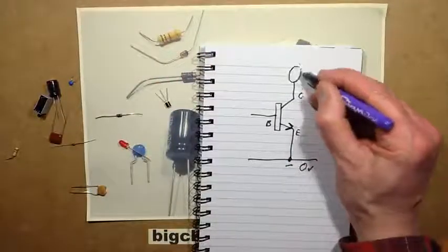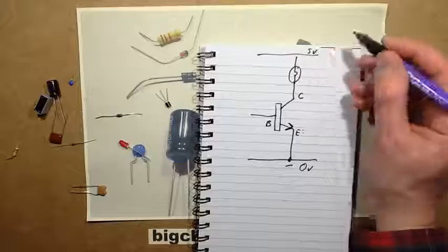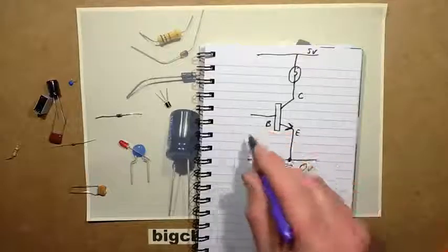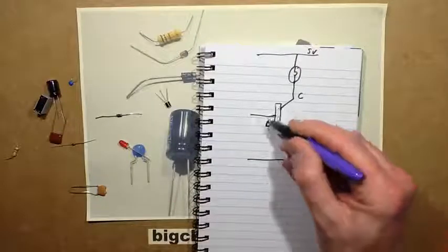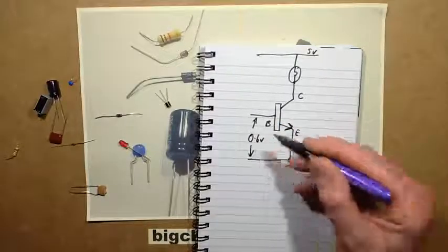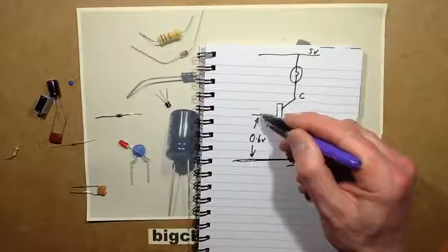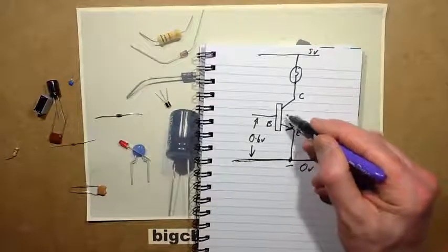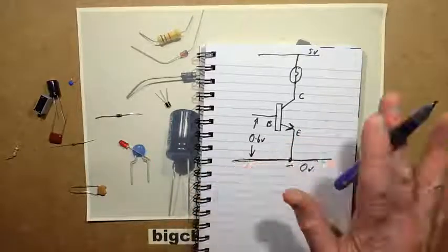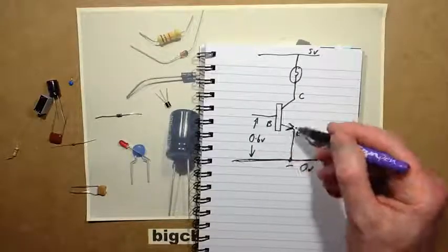Supposing, for instance, you had a small tungsten lamp, and you had, say, a 5 volt supply. If you wanted to turn the lamp on and off, but you only had very limited current available, you can use a transistor, and as soon as you exceed about 0.6 volts, because it's silicon again, that's the standard silicon junction voltage, above the ground rail, the 0 volts, and a modest current, the transistor will switch. A transistor typically has a value called a gain. It's got a voltage rating, a gain rating, and a power dissipation rating. There are lots of other ratings, but let's keep it simple, because in most instances when you're using a transistor, it's going to be an NPN like this.